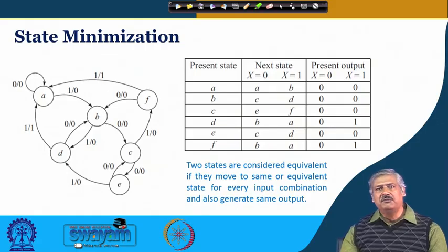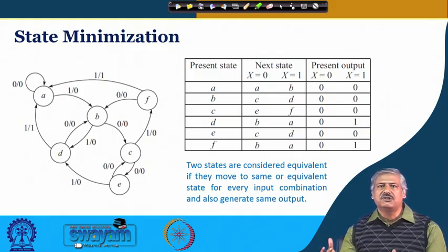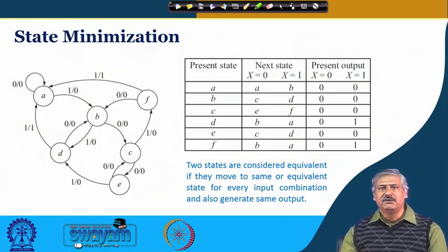There may be more complex problems, more difficult to understand, and logically we may unfurl them and get those states, but it is not necessary that those states to begin with are the most minimized ones. Or, as an implementer, somebody gives us a state transition diagram and asks us to implement it. We can look for whether there is any redundancy, and if we can come up with a minimized state representation, that will help us in reducing cost, time, and many other things associated with it.